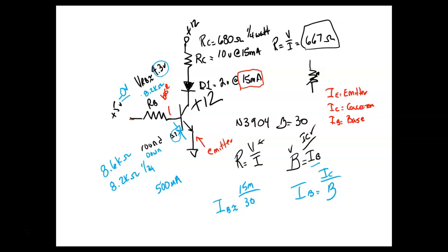But I can check to see if it's blown by just putting my meter across it. So if it's 240 volts at 1,000 amps and I measure across it and it's 240 volts, it's what? It's open, yeah, or blown. If it measures 0, it either means power's not on or the fuse is good or the circuit breaker's good. I've had several circuit breakers that have gone bad, and they're set, right? You say, well, the circuit breaker's not blown. Well, if you measure across it, it should measure what? It should measure close to 0.